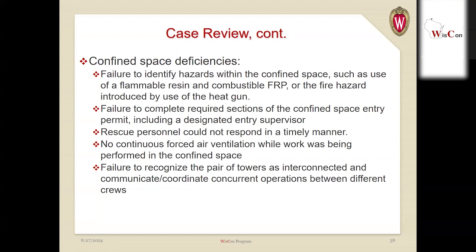Additionally, there was failure to complete required sections of the confined space entry permit, including adding a designated entry supervisor. Rescue personnel could not respond in a timely manner, and there was no continuous forced air ventilation while work was being performed in that confined space. Additionally, there was a failure to recognize the pair of towers as an interconnected unit and coordinate and communicate concurrent operations between the different subcontractor crews that were working.